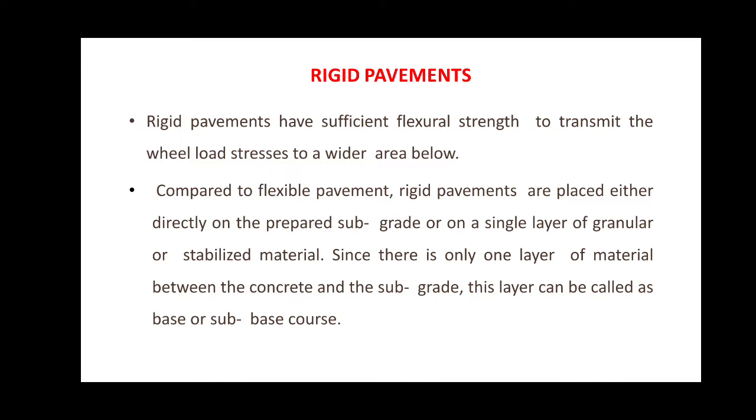An added advantage of the rigid pavement is that no rolling is needed of the pavement layers, and the road, that is the rigid pavement, will be open for traffic after 14 days of curing. Here in the rigid pavements, the force of friction is high between the tire and the pavement, and these rigid pavements are not easily damaged by oil or chemicals.